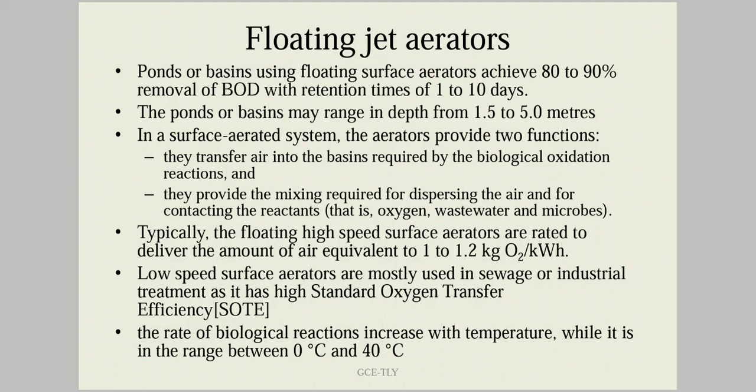A floating high-speed surface aerator delivers oxygen at a rate of about 1 to 1.2 kilograms per kilowatt hour. Low-speed surface aerators are mostly used in sewage or industrial treatment, as they have high standard oxygen transfer efficiency, which is called SOT. The rate of biological reaction increases with temperature in the range between 0 to 40 degrees Celsius. So at about 40 degrees Celsius, there will be a high rate of biological reactions.